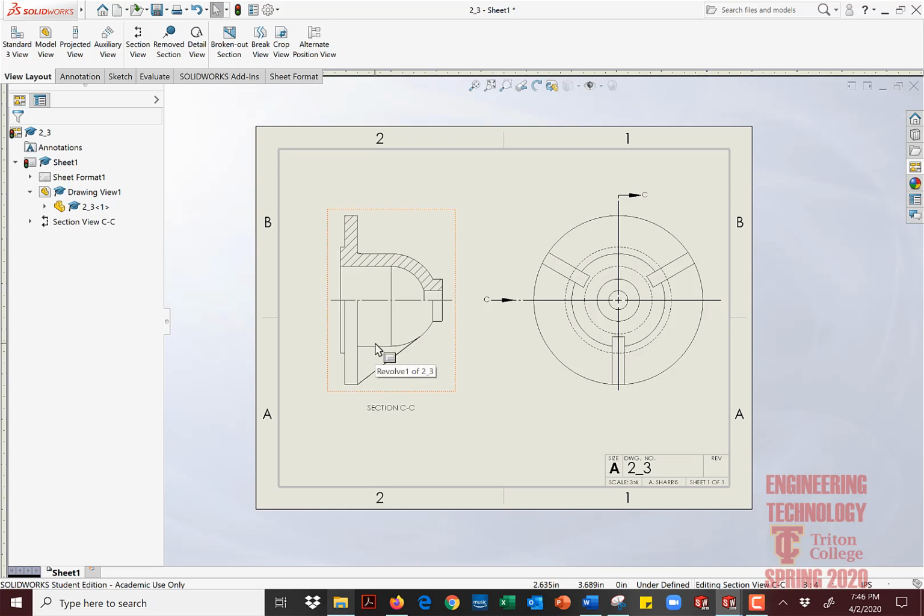So you have to actually correct that. You do not want to turn in a drawing that has a section CC as the only sectional view in your drawing, because people will be asking you, well, where is section AA and where is section BB? Because that is the standard drafting approach to drawings. If I see a sectional CC, that means there should be a BB and an AA somewhere in my drawing. Obviously there isn't.